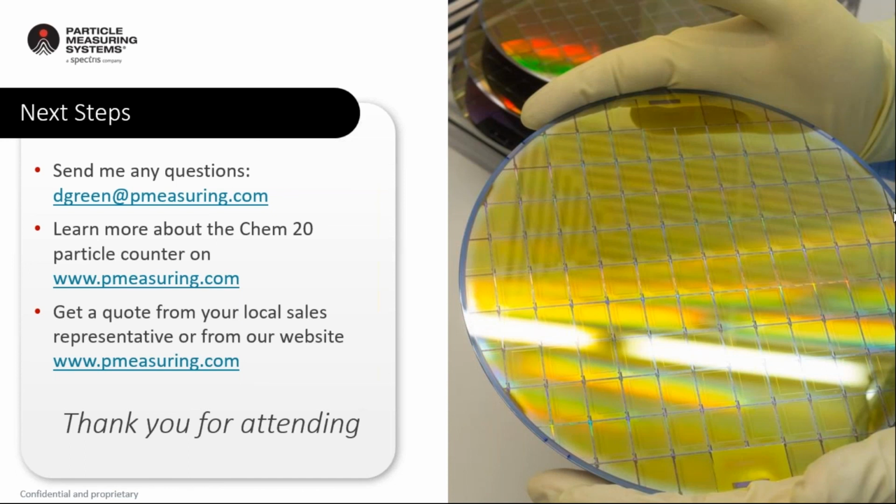There have been cases where there have been pinholes in the chemical lining of the tank, and these generate predominantly particles in the 20 to 30 nanometer range in this particular situation and this particular customer. And so if you were monitoring at a larger size, you just simply wouldn't even know that it was happening, although they were very clear that it was happening on their wafers. And so you'd have this mismatch of, it seems like the chemical's good, but the wafers are having a yield problem.